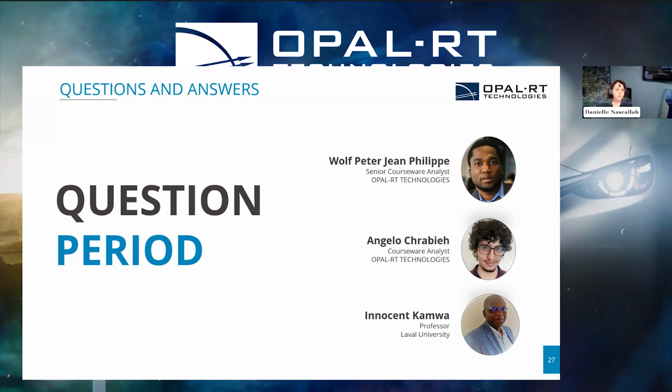Who is ready to answer this question? Wolf, Angelo, Inosa? The response is yes. You can open ECF files which were created in EMTP in HYPERSIM. However, while some components are compatible, the control part will not be compatible. You will need to draw your control scheme again in HYPERSIM, but the power components will be compatible.